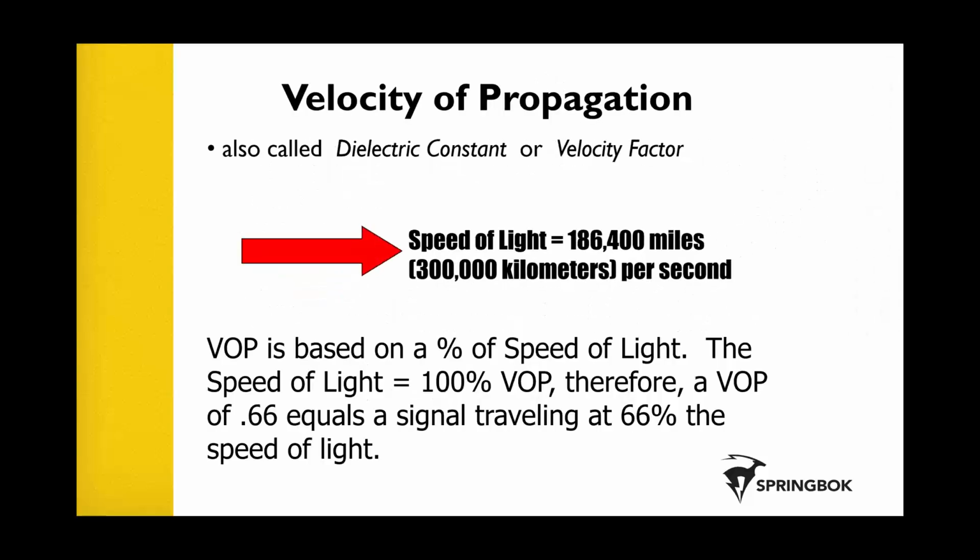Okay, so the biggest thing that you're going to have to worry about as far as calibration on the TDR goes is going to be the velocity of propagation. Most people have heard of velocity of propagation, but let me just explain it to you in a real simple way. Velocity of propagation, or sometimes it's called VF or velocity factor. Sometimes it's just displayed as a 2-digit or possibly a 3-digit percentage number, or a decimal number.